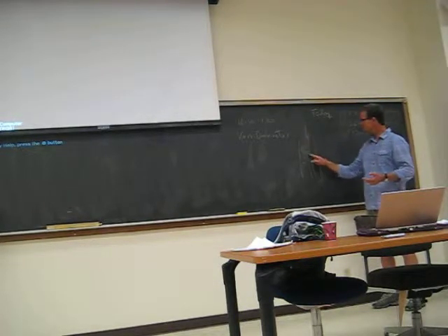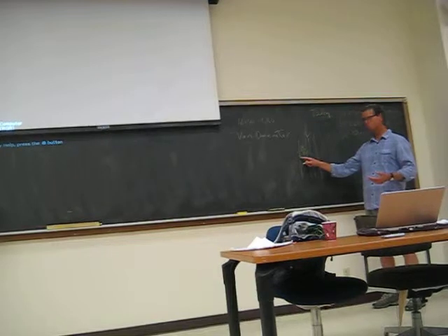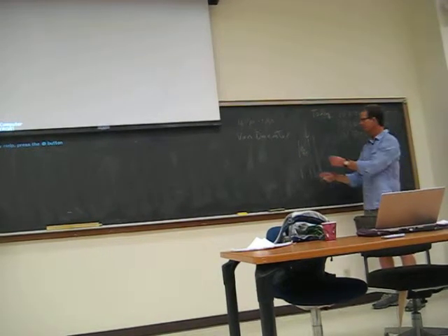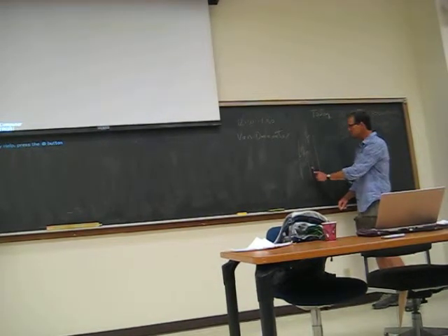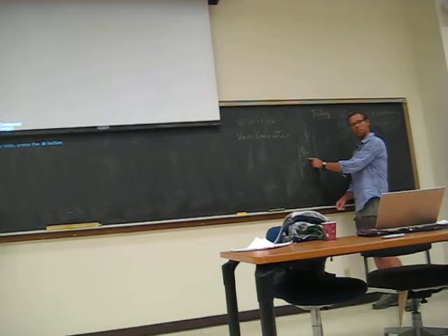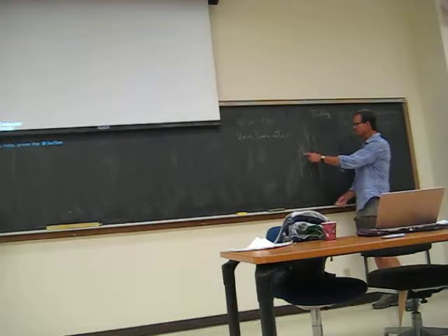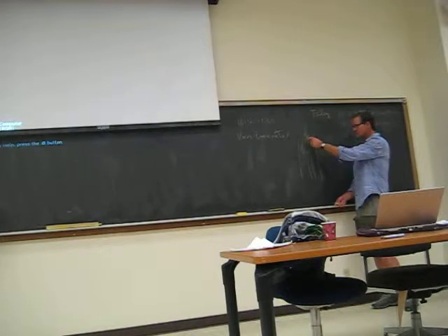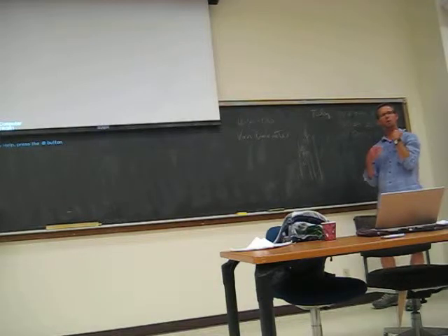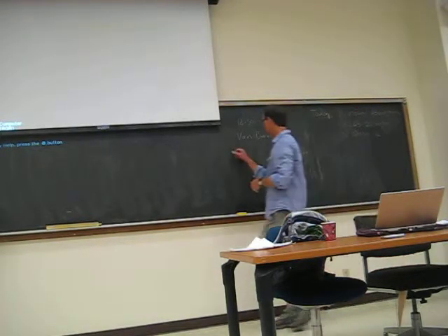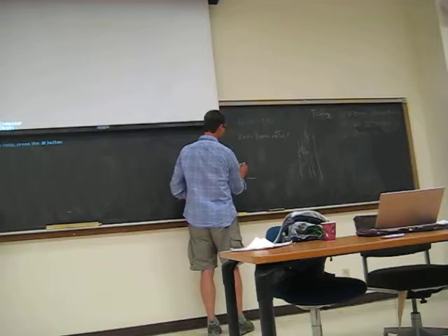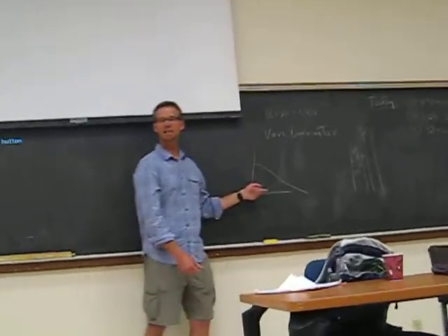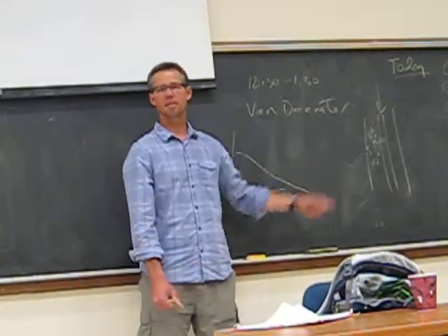So as this flow rate declines and the current does not change, the residence time of the fluid in the suppressor increases because the flow rate is reduced, right? And so you have a higher concentration of protons diffusing into the eluent space because it has a longer residence time in the suppressor, and we're over-suppressing. Many of you recall that you would see these baselines diving down and getting really negative, right? And it's because of that, I think.